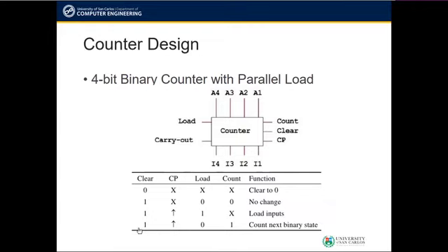Lastly, we can see here that when we have a 1 input on the count pin, 0 input to the load pin, and a rising edge on the clock input is detected, the counter simply performs counting.